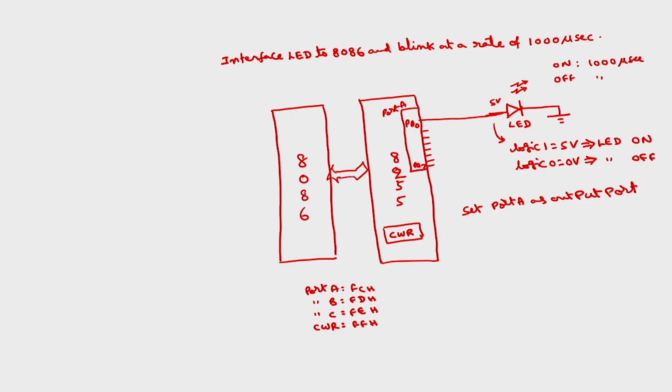I will discuss the different modes and what happens in them later. So I will take simple mode 0, which is called simple IO mode. Any port can be programmed as either input or output. And what about port B and port C? I do not care. Port B and port C can be either input ports or output ports, and port B can operate in either mode 0 or mode 1. Okay. I am not interested in those ports because I am not using them. Okay.